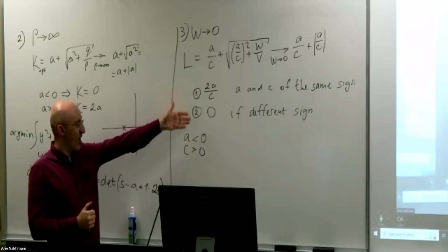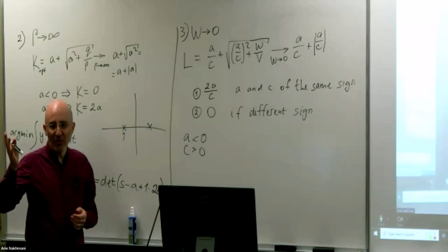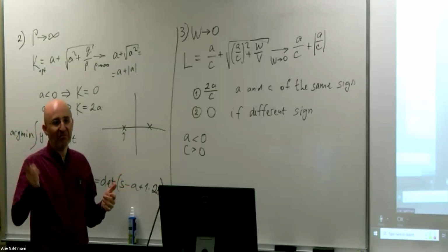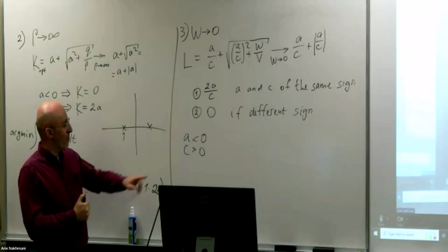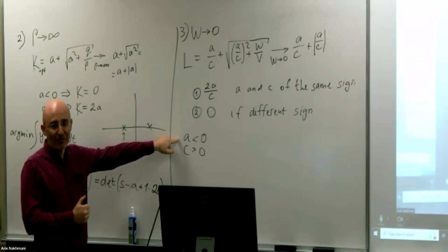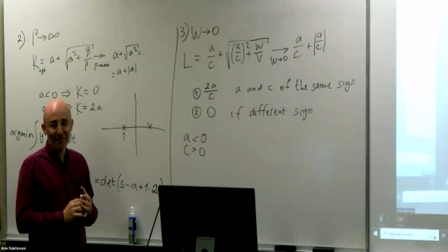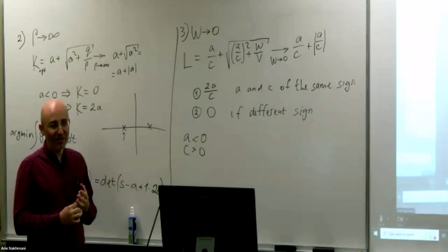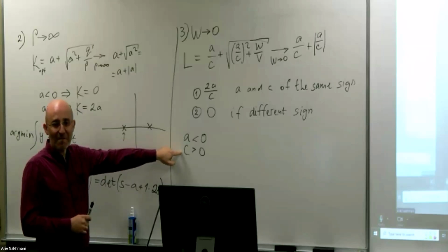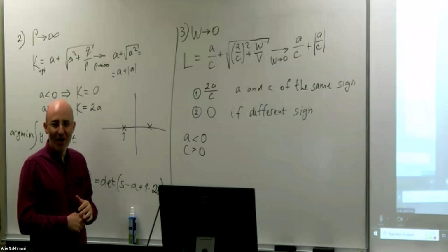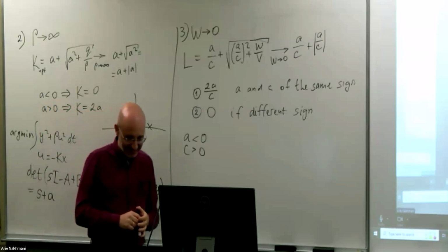Okay, and then Kalman gain will be just 0. Just multiply error by 0 and don't use that error. Just use your model as is, ideal model. This is a condition, right? Now, it's interesting that when A is unstable, this is not the answer, right? Because you need to be very careful what happens when A is unstable. But the trickiest part here is when A is unstable and C is negative. This is the tricky part to interpret, like why you still cannot use your model anymore. This is a deeper question. Think about that.